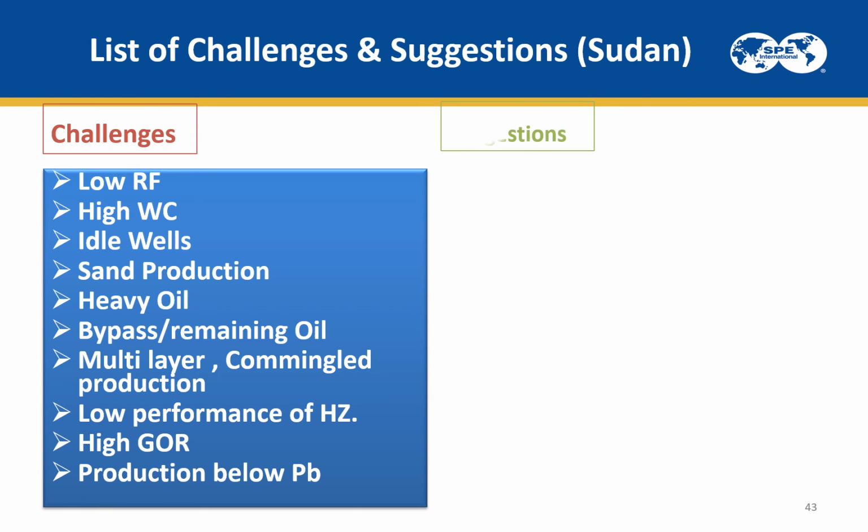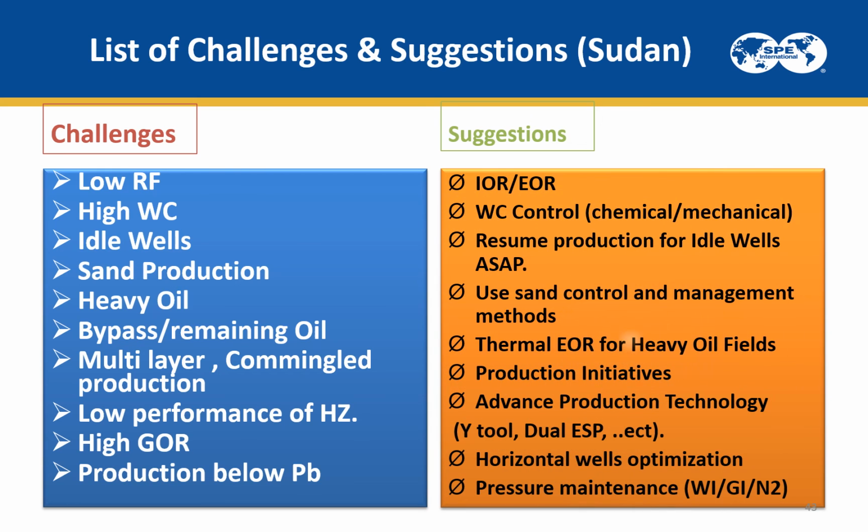As a quick suggestion for these challenges, we need to think about using EOR methods for water control. It can be chemical and mechanical methods. For the idle wells, the assumption is that production from these idle wells should restart as soon as possible. It will help to sustain the production. For the sand problem, you can use sand control and management methods. For heavy oil, the thermal EOR method is recommended.